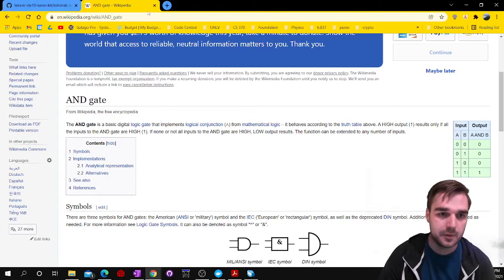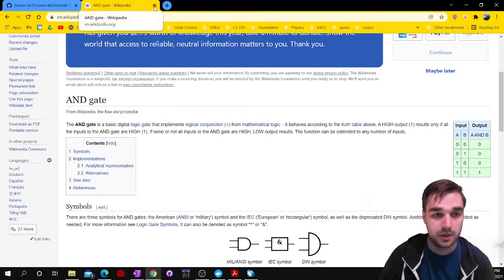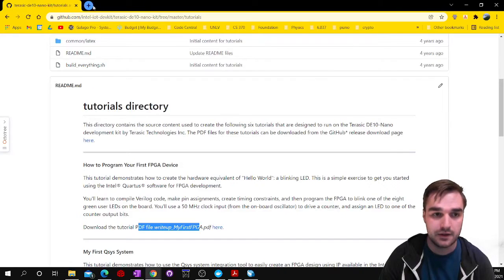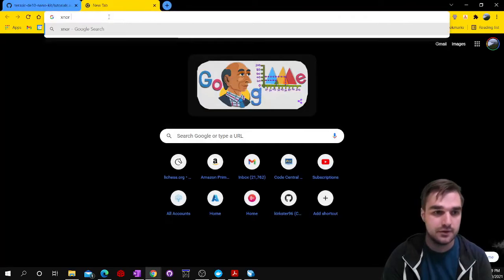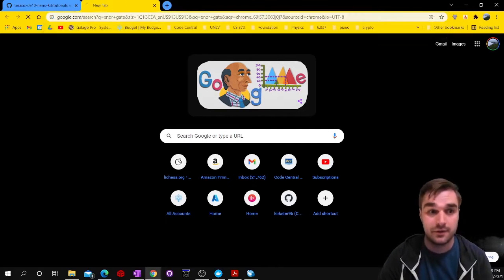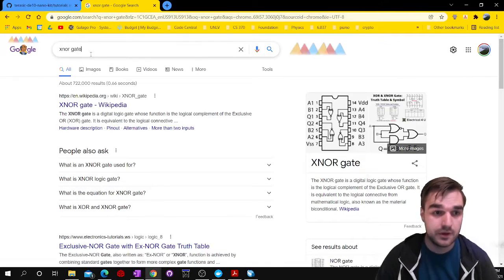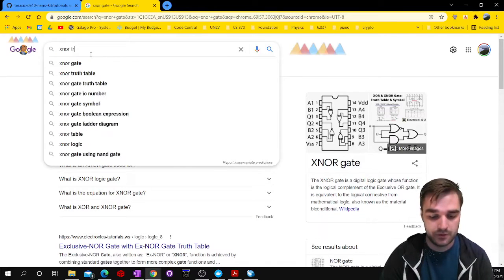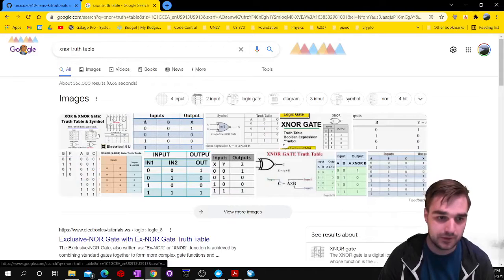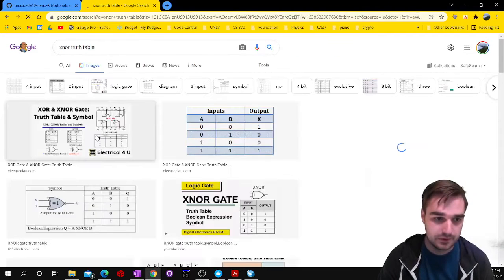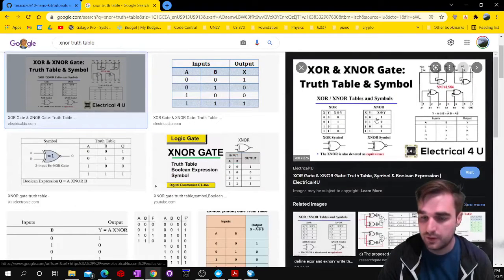So let's say we're working with a new gate. We're going to be working with the AND gate in this video, but let's say we're going to do the XNOR gate. And you're like, what the heck? That sounds crazy. What does it do? You just type in XNOR, the name of it, and then truth table, and you will see the truth of how this gate works. So we have the XOR and the XNOR. There's the XNOR. X and Y are the inputs.